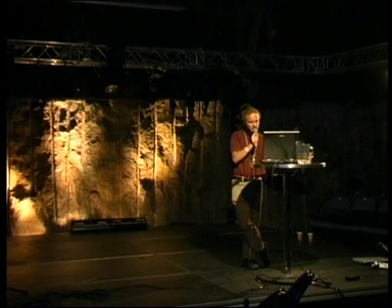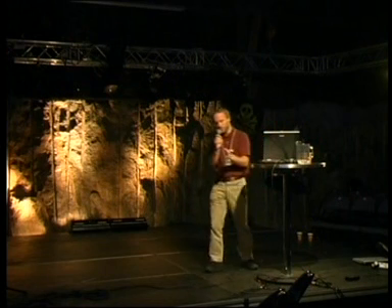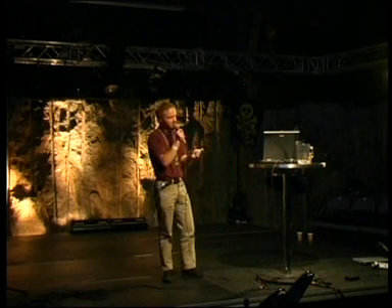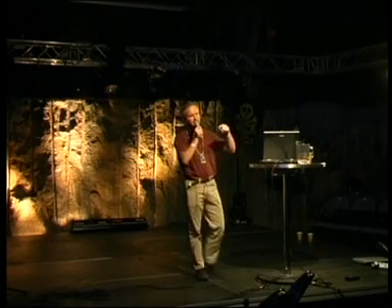So, a conditional branch. Normally, when you have the short form of the conditional branch, you have 8 bits for the branch offsets, which means you can branch up to 128 bytes in each direction. But the lowest bit of this one is always 0, because this instruction is always at even offsets.